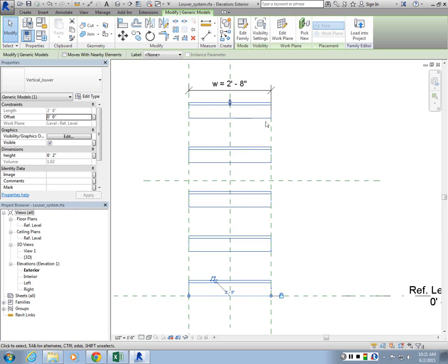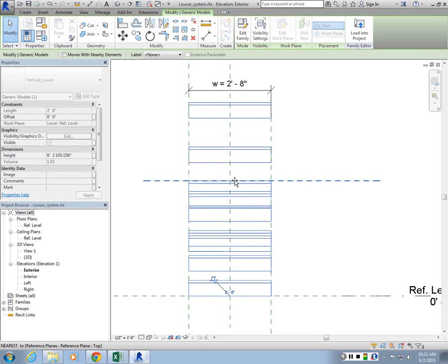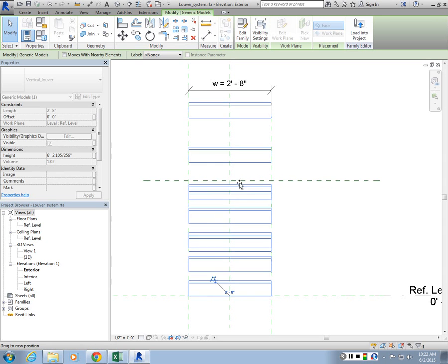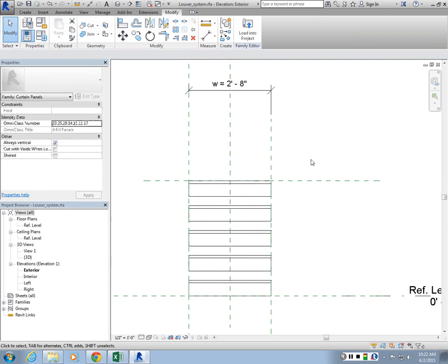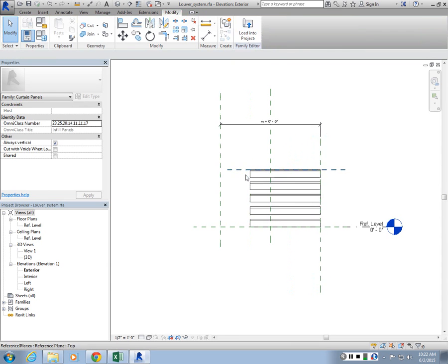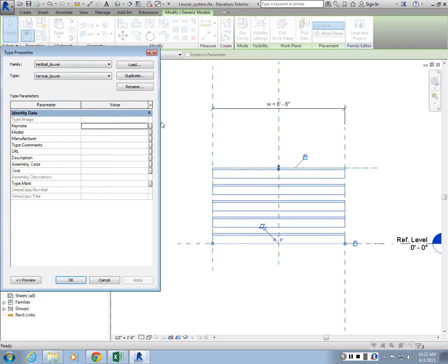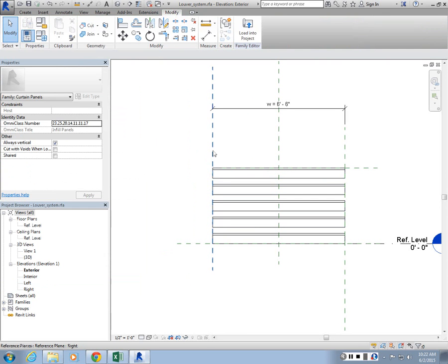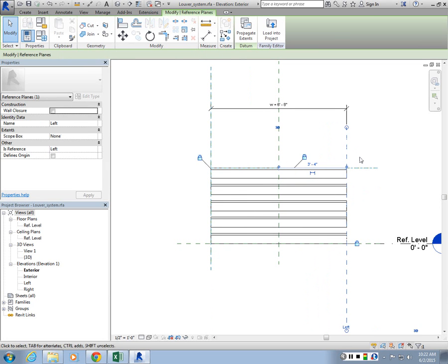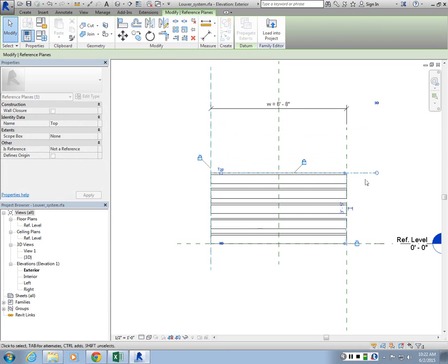If you can't see it, that means you need to create a vertical annotation inside the array, because this allows you to snap or reconfigure the height parameter for that array. So I'm going to move it here and lock it. So now what I have to do, let's move it here. Let me see if we have, let's do an align, lock it there. This side is locked. So it's basically flexing pretty well, right? So the top and the bottom, everything is locked.